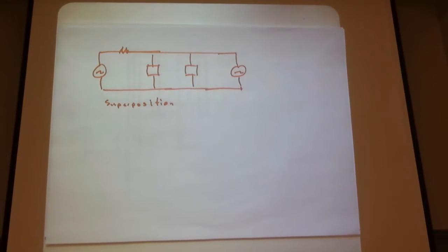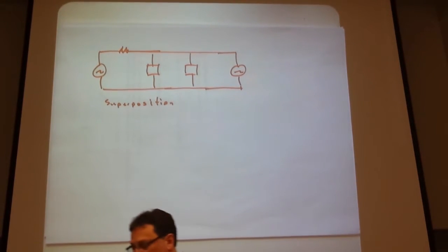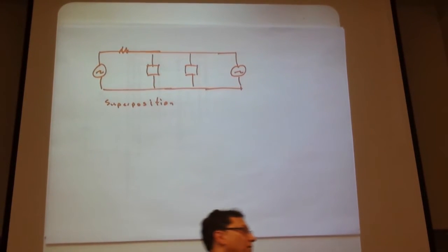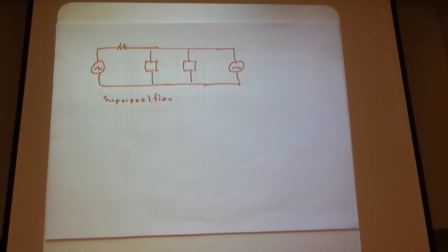We talked about Thevenin resistance, Thevenin equivalence, impedances, nodal analysis, KVL, KCL, all that fun stuff. We can apply everything we did in Unit 1. Superposition: turn off all the other sources, off for current sources means open, off for voltage sources means short, et cetera. All the fun stuff.